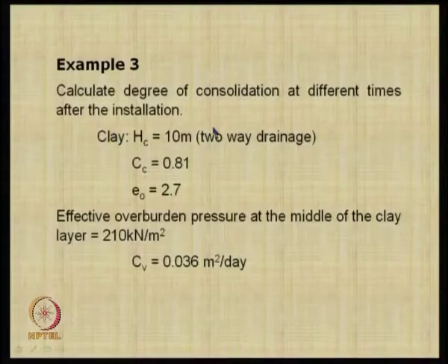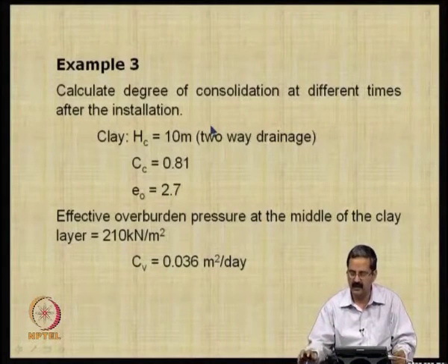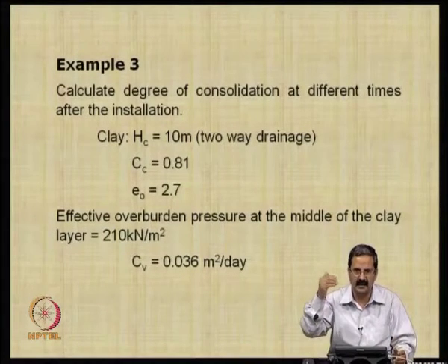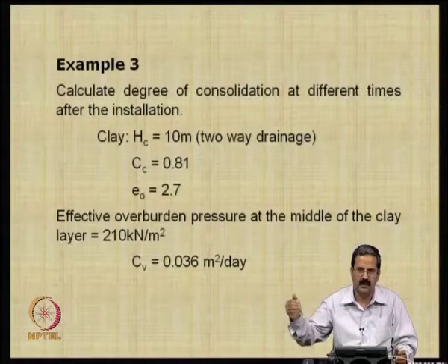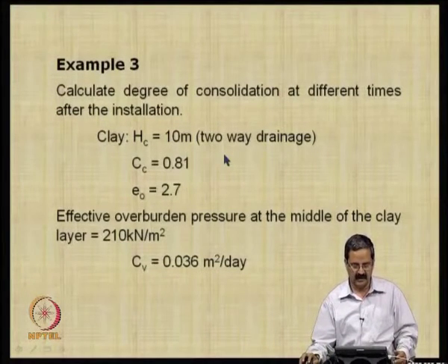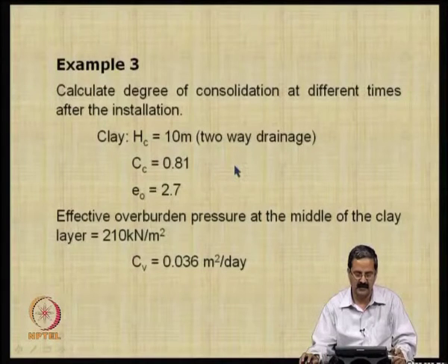another important point that we have to calculate here is that you should be able to calculate degrees of consolidation at different times after installation, because we know that this consolidation can be very low, and then we would like to increase the consolidation using the sand drains or prefabricated vertical drains. For the same example, or rather a similar typical example,